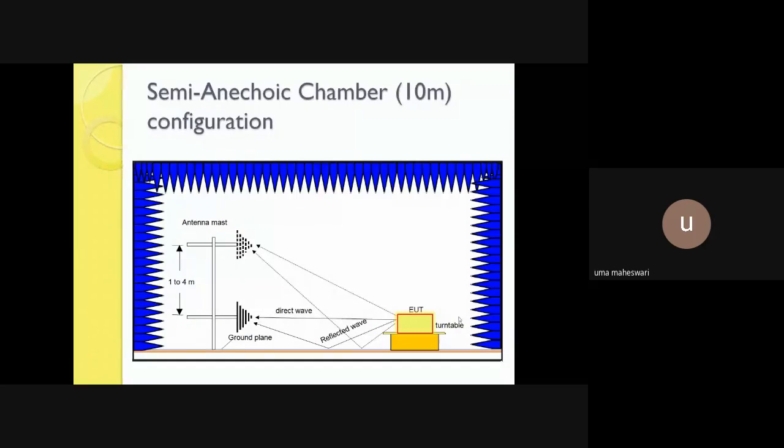Inside the chamber there will be an antenna to emit the interference, that is radiated. It can be direct or indirect. Direct means it will be connected through wires. Indirect, for susceptibility, means it is transferred through the antenna. Radiated waves are passed to the EUT, and we measure how it performs in these electromagnetic wave situations.